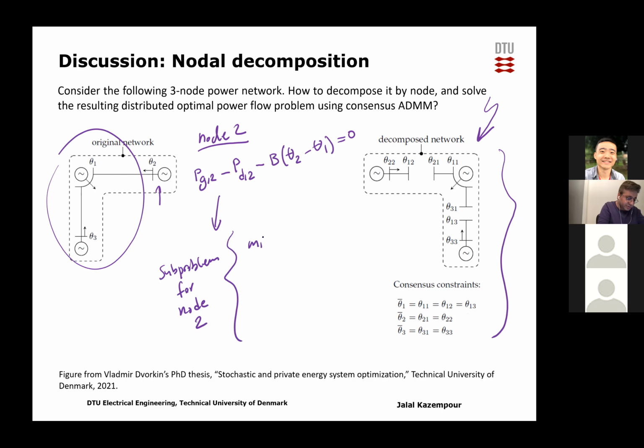So here the objective function is the cost, I would say just the cost related to generation located at that bus, subject to, assuming that the demand is inelastic. So also we have the limitations for PG2, so f of PG2 is lower than or equal to 0, some functions related to the generation at node 2.